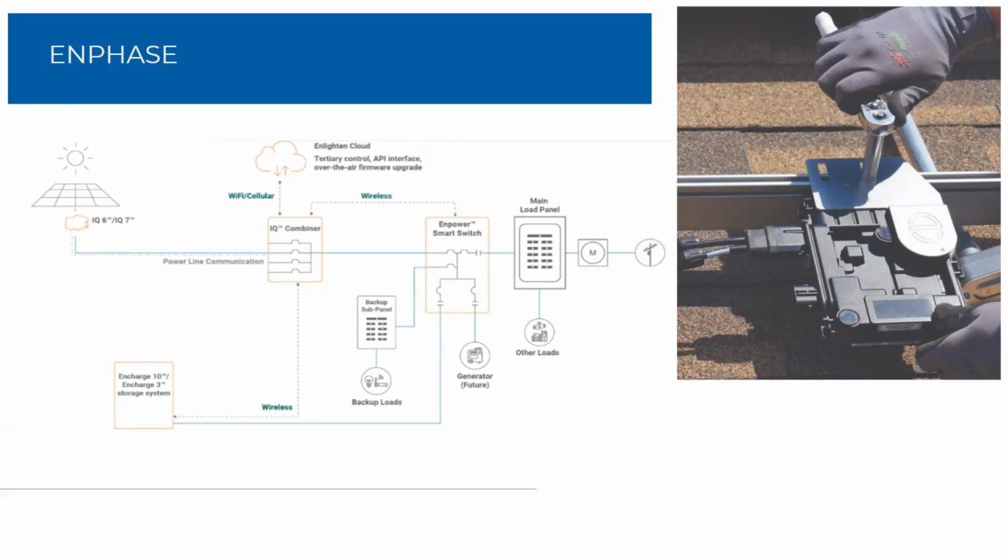Rule of thumb, just based on what we're seeing, people are typically installing 2 or 3 N-Charge 10s. And not to have option paralysis here by saying, how many N-Charge 3s, how many N-Charge 10s do I need? If we stick to 2 or 3 N-Charge 10s, that's in the typical scope of what homeowners are getting installed. So then the main panel would have any excess PV that might go out during an outage.